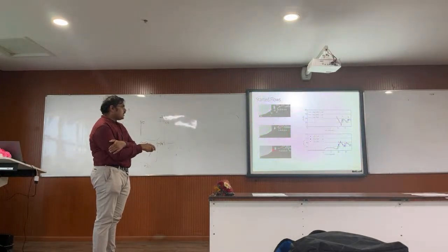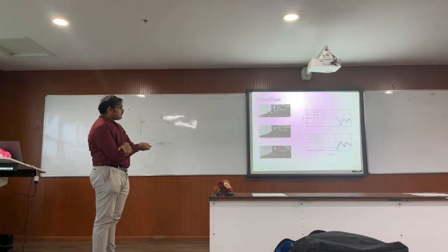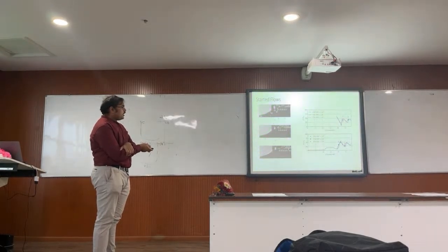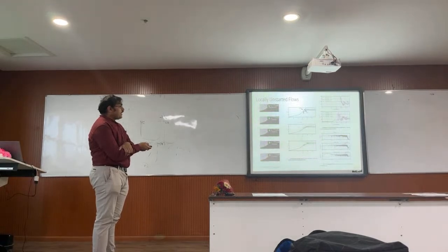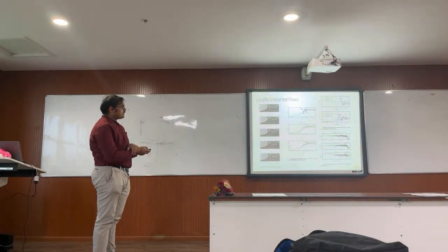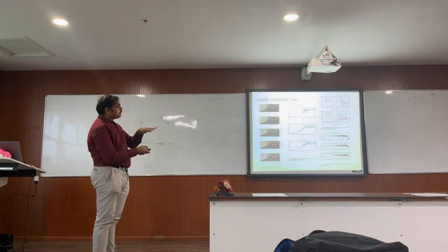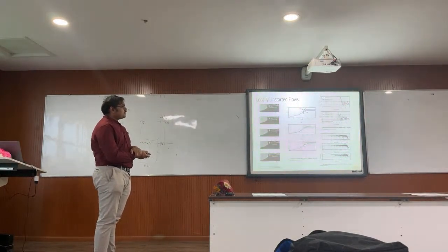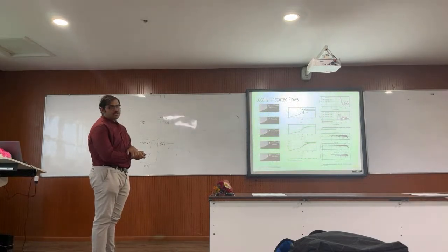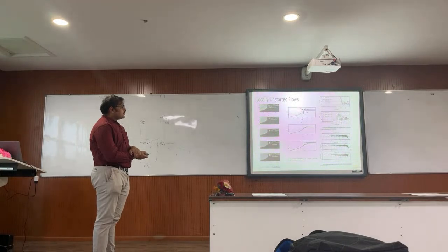But the only thing is, as we kept on increasing the contraction, making it more and more contracted at the throat, at the isolator, then we start seeing some strong shocks coming out from this last pressure transition. But otherwise, the pressure profiles were all similar. So finally, we get into a stage where the contraction is so high. So this actually is more like a straight line, and in this case, the cowl has been bent up actually. So this is slightly to give us this condition of high contraction ratio. When we go into these regimes, what we see is we get a shock system of this kind.